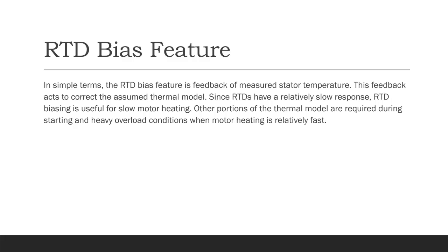The RTDs are a little bit slow to respond. Heat is somewhat slow to make it into the stator windings, especially when it originates in the rotor most of the time, especially in a high torque application. So the RTD biasing is not a motor protection strategy on its own. It is a strategy that goes along with the motor thermal model.